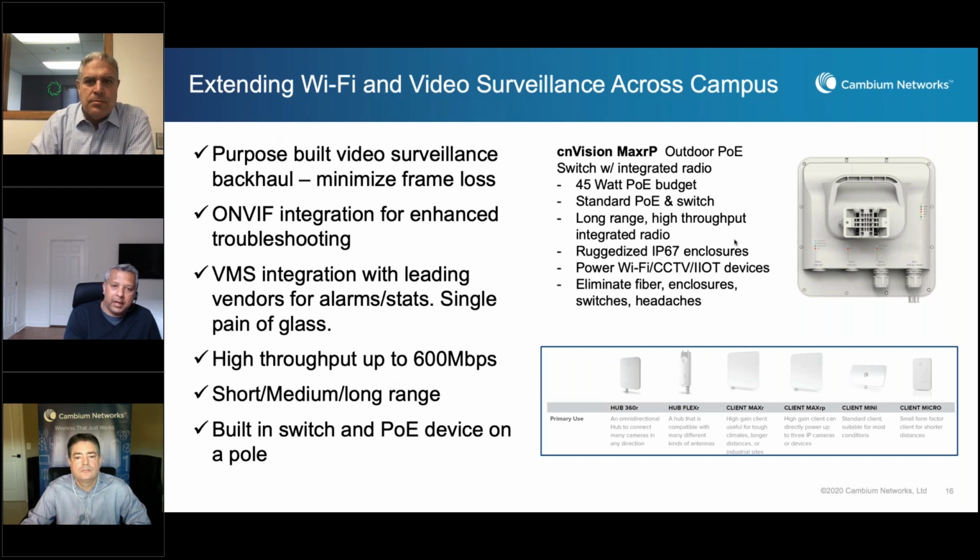Bottom right-hand corner, you kind of see the portfolio. We can have a separate session on this, but I just want to highlight that a pole mount switch with an integrated radio and a 60-watt power supply with a 45-watt power budget out of 3 PoE ports all of a sudden eliminates the need for a separate switch and separate backhaul connection, and brings the cost down, with ease of use up and failure points down to a smaller number of scenarios. So we're excited about this product, and I think it has a lot of application in the education space.